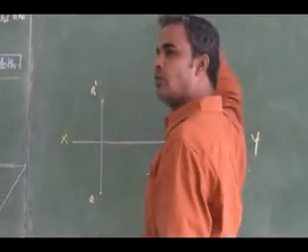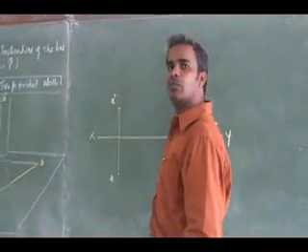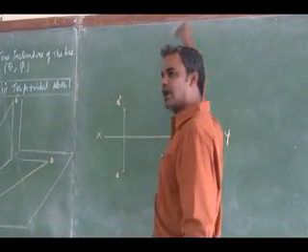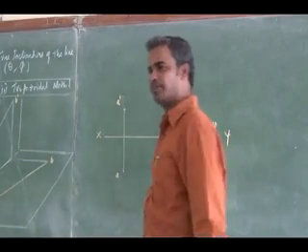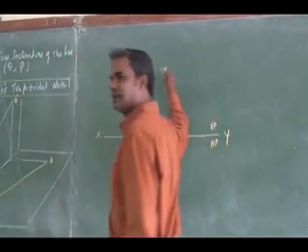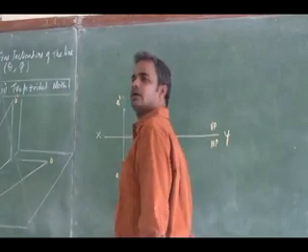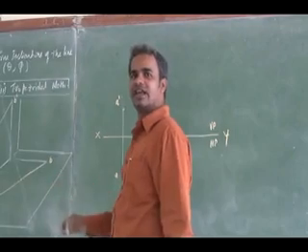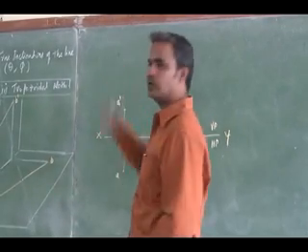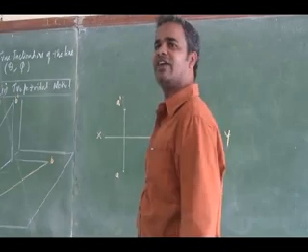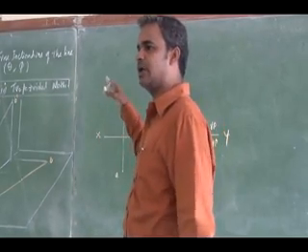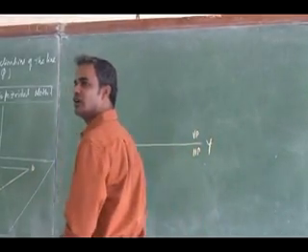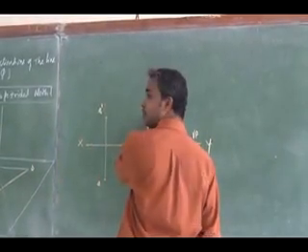So where is the other end B's projection going to be? The horizontal line drawn parallel to that is the locus of end B. The bottom one is the locus of end B, the top one is the locus of projection B dash. Is it clear? Using the other two data, I can straight away draw the locus, using the above distance of end B, that is 45 mm.